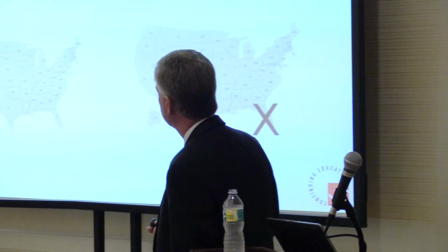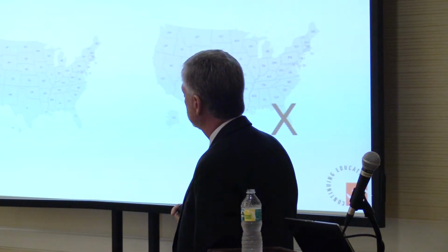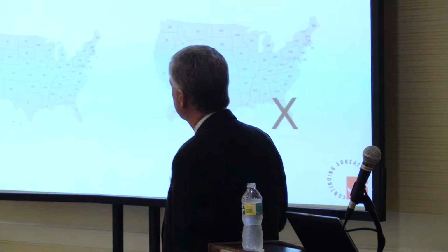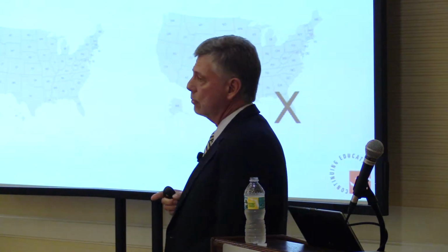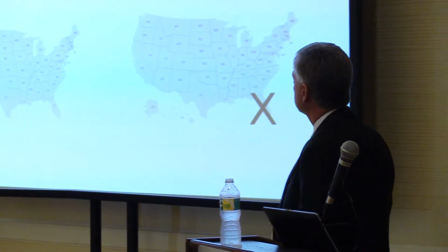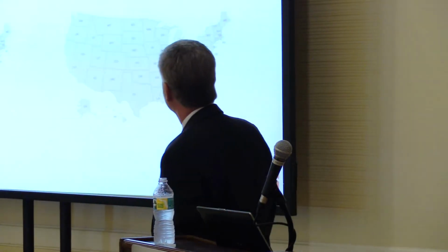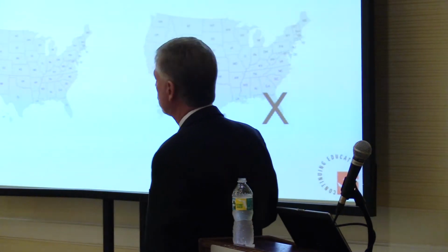2013 7.1 standard, which says that in critical spaces, air changes per hour can be reduced during the unoccupied times of day. It also allows VAV systems as long as the pressure relationship and minimum air changes per hour are maintained in non-critical spaces during any time of day. This was true in every state in the United States with the exception of Florida.